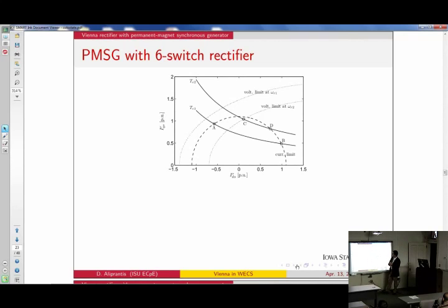And then the other limit comes from the voltage. As the wind turbine speeds up, as the wind blows harder and harder, you need more and more voltage to drive the currents into that machine. And so at some speed, you have a voltage limit, which is basically, this line is part of a larger ellipse, which is like some huge ellipse here on this plane, which I'm not showing. And as the speed increases, this ellipse shrinks and shrinks. So this is a voltage limit at one speed. This is another voltage limit at another speed.